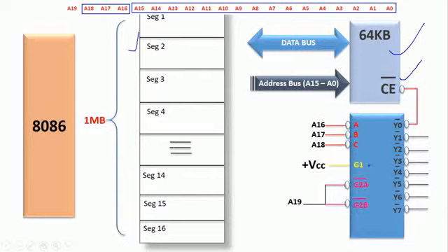But even though we have the input combination, we are not going to get the functionality, because we are supposed to enable the activating signals of this 138, the address decoder. So for the active high signal, I am directly applying plus VCC, and I am using the A19 line to activate the active low signals of the 74LS138. Sorry, it is a 138 only.